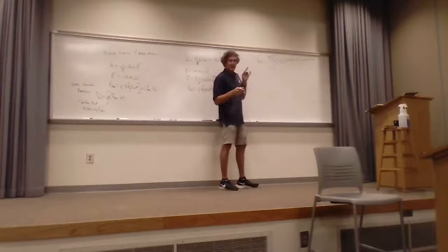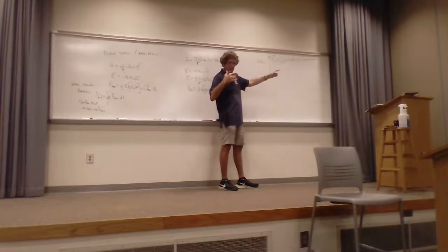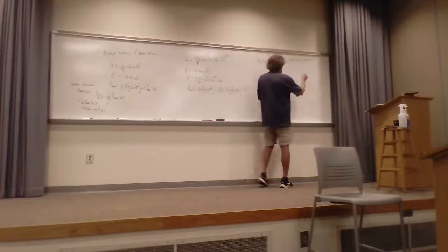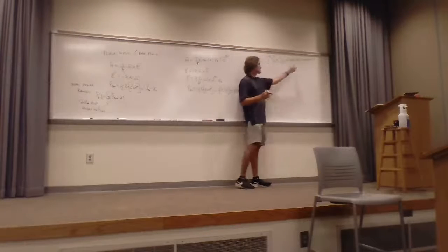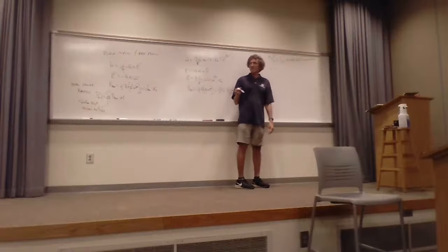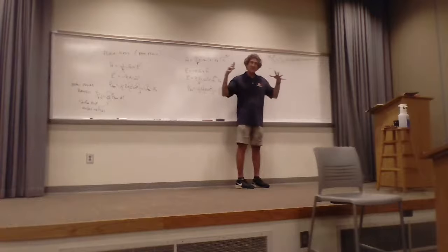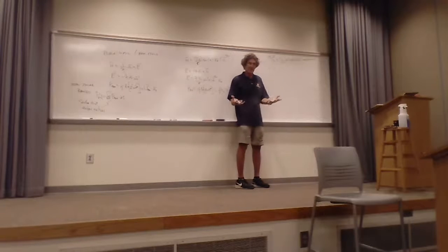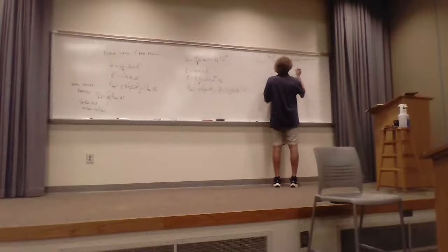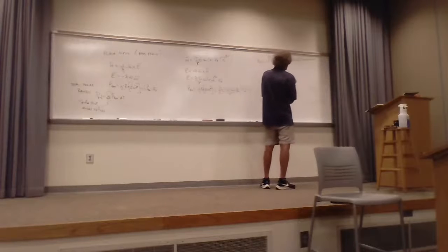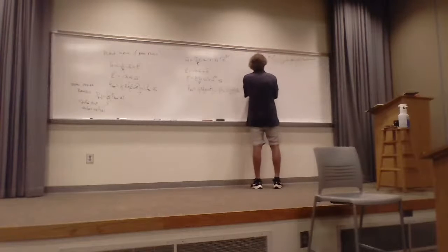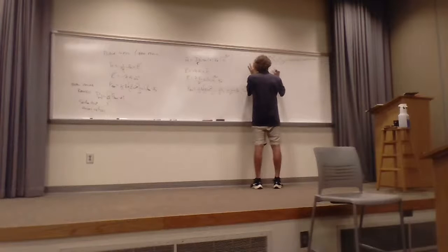One thing you're going to see right away looking at this, AR dot AR is 1. So get rid of that. Now, you see how the r squareds cancel? If I got something that's a function of r, I messed up. The total power leaving an antenna has nothing to do with the radial distance of the shell you're looking at that it's penetrating. So I see that r squared goes away. Then I have sine squared theta, sine of theta. I'm going to do this once. So this is P rad, and this is equal to the integral from 0 to 2 pi, right here.